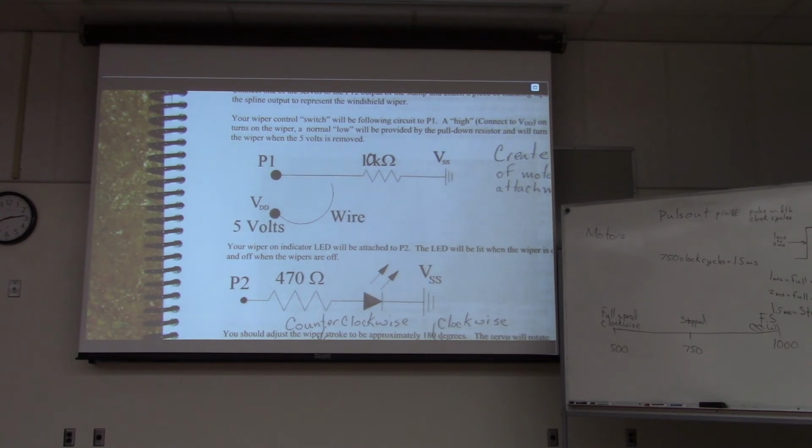Question about VDD and VSS. So VDD is high voltage and VSS is low voltage. Yes. I've been understanding it as positive, negative, VDD being positive, VSS being negative. Is that correct? VSS is really ground or 0 volts. But yes, VDD is a positive 5 volts.